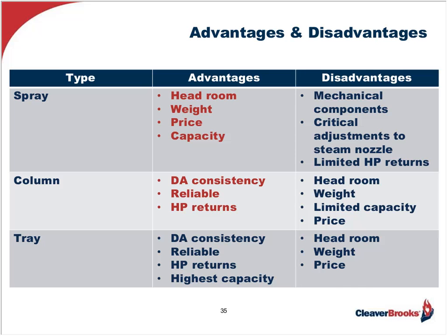So, in the final analysis, and when everything is said and done, all of these deaerators eliminate oxygen to 0.005 cc's per liter, which is about 7 parts per billion, a real dry martini. It's just a matter of choosing the one which best meets your headroom and floor loading needs, your capacity and system requirements, and of course your budget.